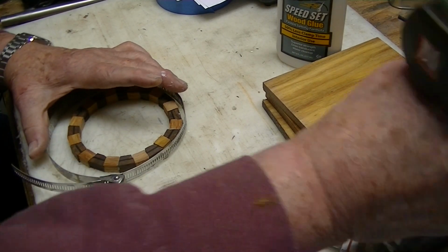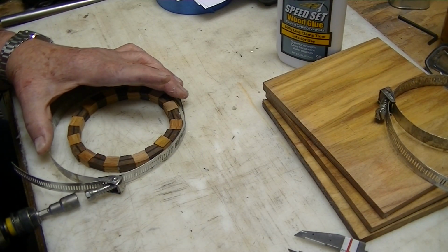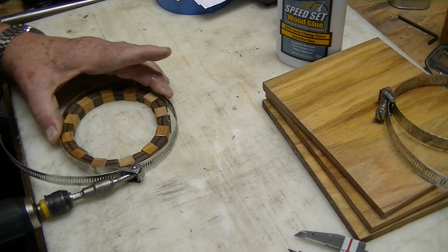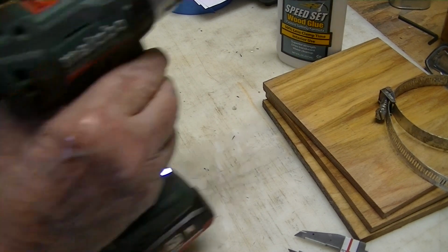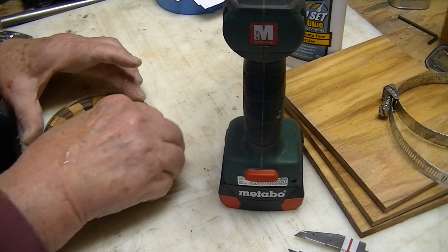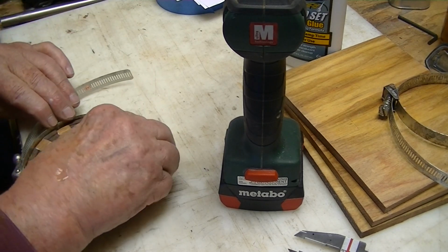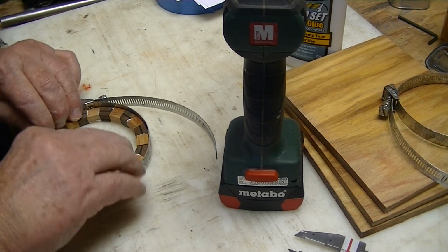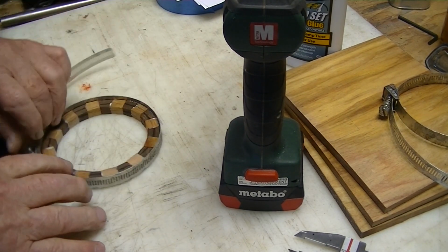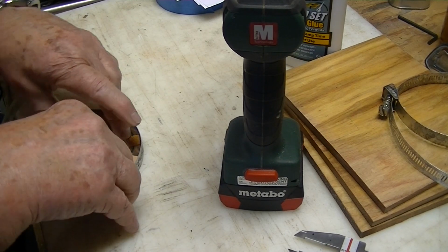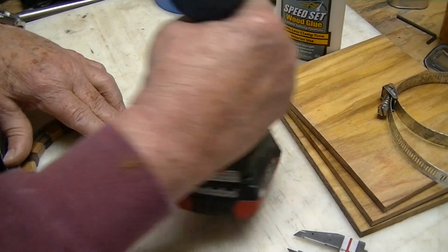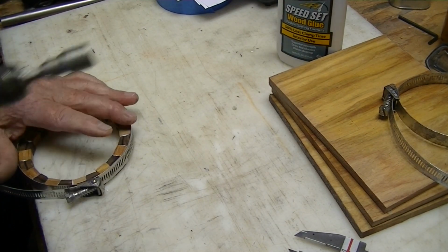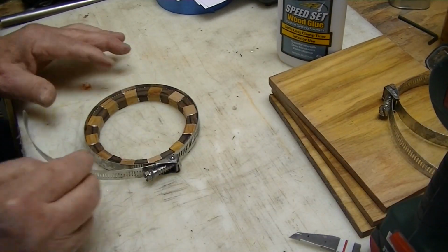There's all 12 segments and 12 spacers, 24 pieces. And we'll just clamp this now nice and tight, but first of all, loosely. And I'm going to go in and make sure every piece is pushed snugly against the edge of the band clamp and flat to the glue-up surface. Check each one individually, make sure it's in place. And as soon as I'm satisfied, I'll go back to my power drill and tighten the clamp for its final position while the glue dries. Okay, there's a ring. Done.